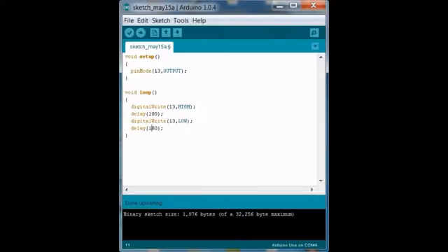So the only thing we have to change in our code is changing 13 to 8 because we changed the pin reference. So that's all we're going to do. All the points where you see 13 is still going to be output because it's outputting information. And we're still using digital write because we're still using digital pins, which are here. So we're going to change all places we have 13 to 8. And now we're going to upload this sketch.